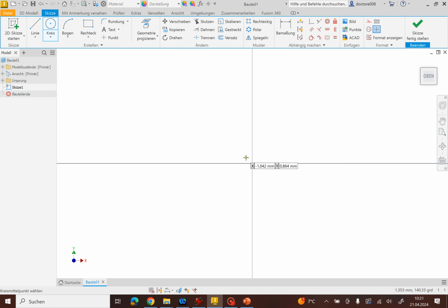If it's yellow, then it's anywhere. You see the coordinates X and Y. But when it catches a special point, then my mouse dot turns green. So now I got it. It's green. So I click the left mouse button and then release it. Don't hold it down. That's wrong. Take your finger away from the left button, and move your mouse.